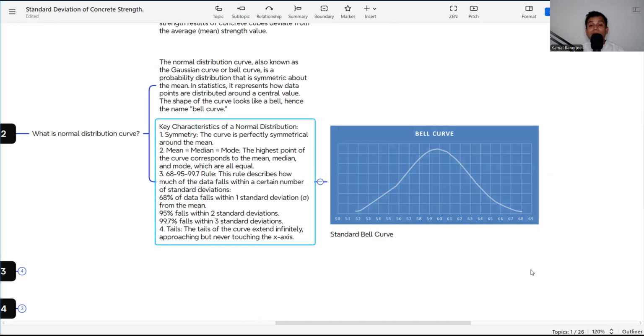So now if we are designing for M50 and we have characteristics, we are giving 1.65 into 5, we are assuming that the standard deviation is 58.25. So we are designing the 58.25 for the target strength, and we are getting a mean maybe 55, 56. So plus minus 1.65 sigma, this 95% will fall inside the result that is satisfactory, that is above the 50.